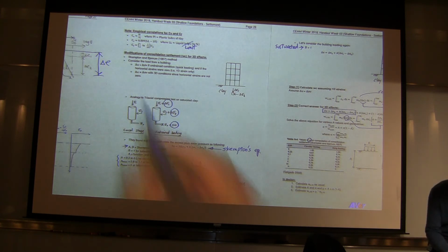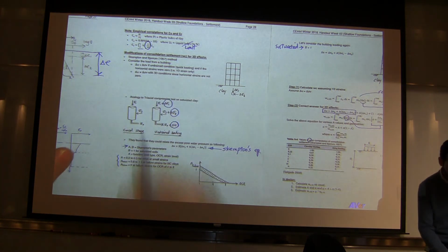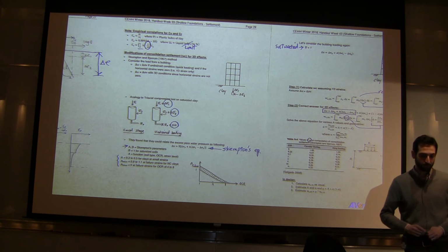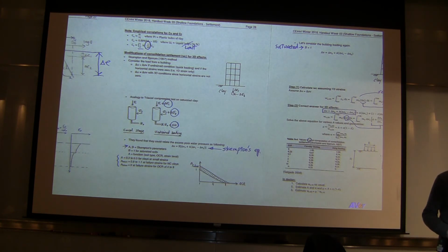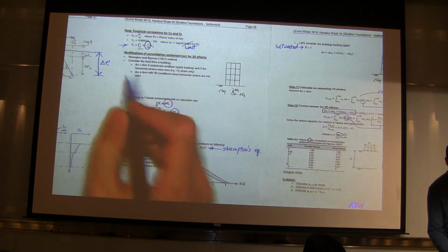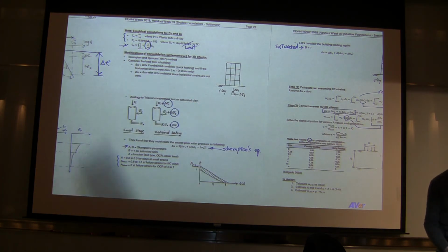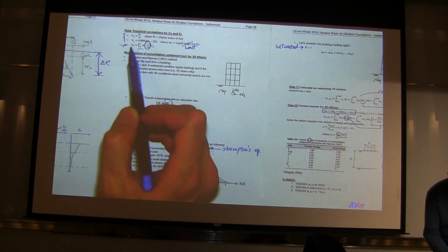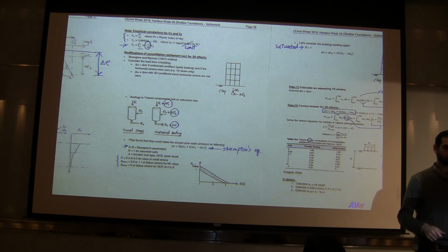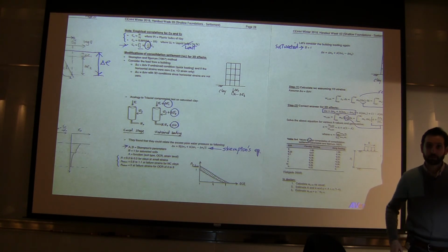And it's very typical to use 1/10 or 20% of CC as a CR. This is very common too. In fact, a lot of times it's hard to get the CR from lab tests. So you might send a sample to a lab and get the CC value, and then when you're doing your calculation, you just multiply it by 20% or 10%. That gives you the CR value, and then you do the rest of the calculation.